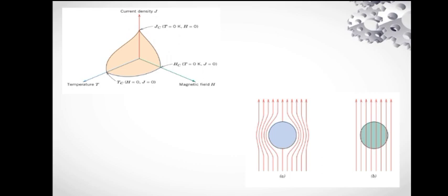The superconductivity phenomenon has been satisfactorily explained by means of a rather involved theory. In essence, the superconductive state results from attractive interaction between pairs of conducting electrons. The motion of these paired electrons becomes coordinated such that the scattering by thermal vibration and impurity atoms is highly inefficient. Thus, the resistivity, being proportional to the incidence of electron scattering, is 0.